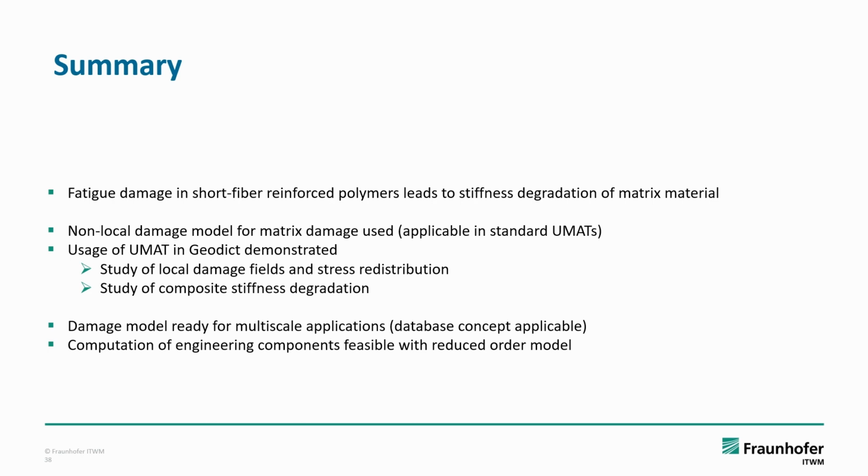We demonstrated the usage of standard UMATs within GeoDict, and we are able to study the local damage field and the stress redistribution due to the UMAT implementation of the damage model. Also, from a homogenized point of view, we are able to study the degradation of the stiffness of the composite.